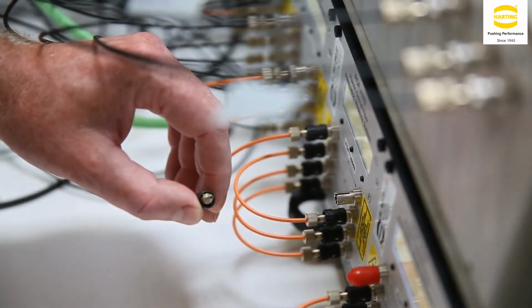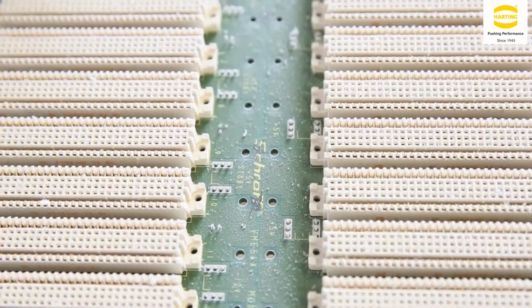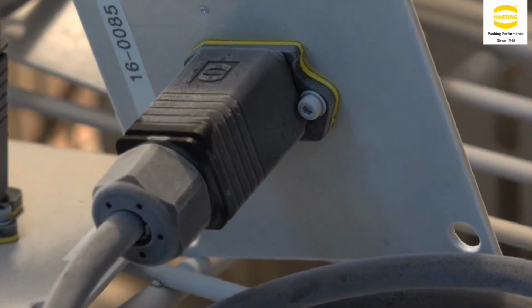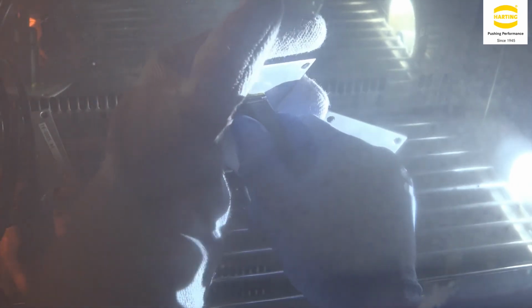What's also very interesting is the functionality of our products at the different limit temperatures. For example, if we have a plastic enclosure and this plastic material is very prone to get brittle in the influence of cold, we can make a functionality test like mating cycles or locking cycles at the cold temperature and see if the locking mechanism will fail or if it will pass, if something might break, for example.